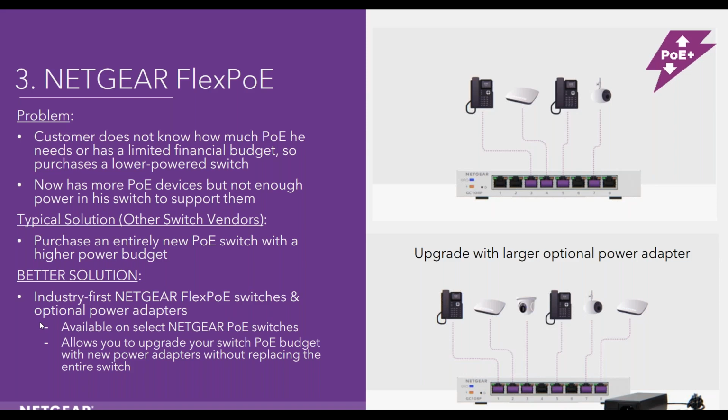But they may also have the plan to upgrade the PoE devices or their PoE network later, so they don't have to purchase an entirely new PoE switch with a higher PoE budget and higher cost. They just need to purchase the additional power adapter and change it to the existing PoE switch to upgrade the PoE budget. So this is our industry first Flex PoE feature. And it's very simple to use.